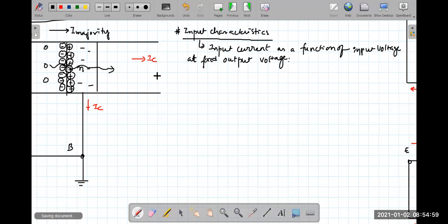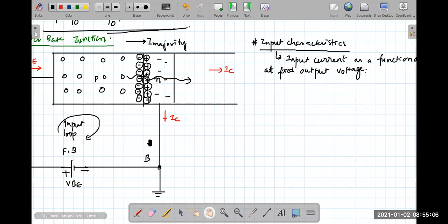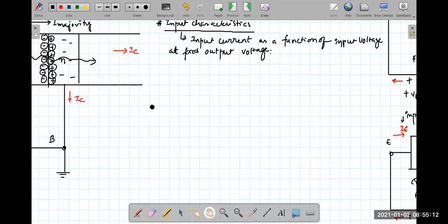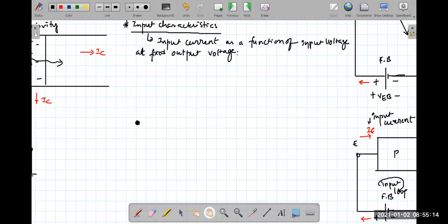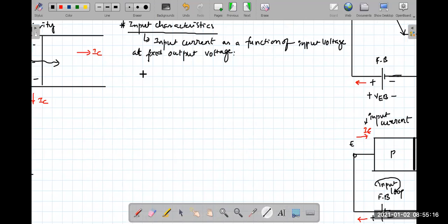So coming to here, all we see is a diode which is under forward bias condition. First you need to apply some voltage so that it will start conducting. After that, the current will rise exponentially. So Vivek is correct. Here you get a curve which is rising exponentially.